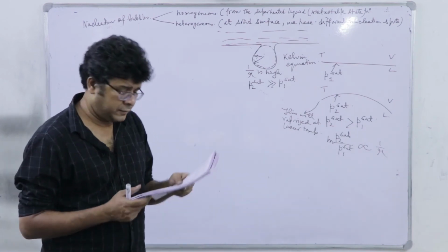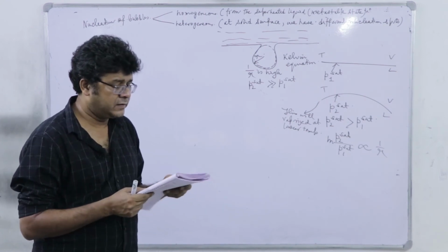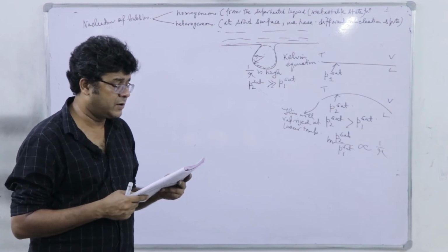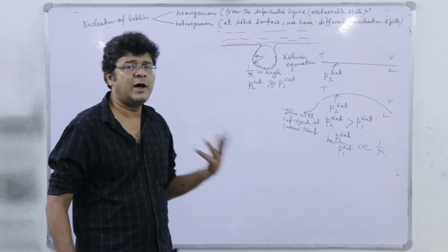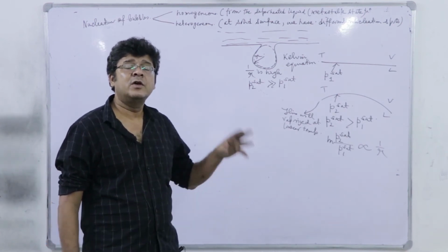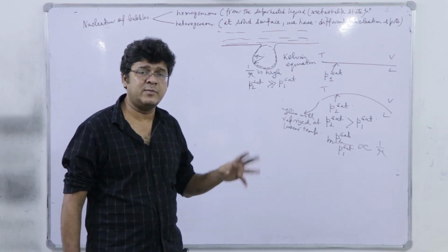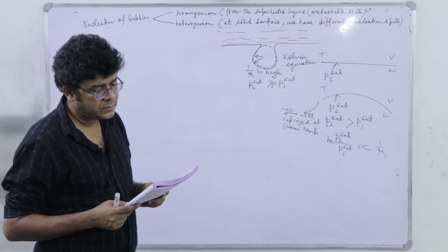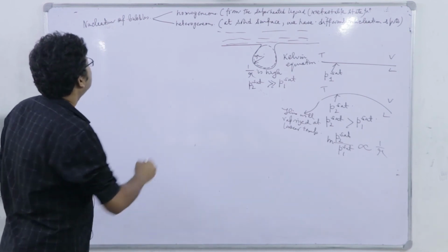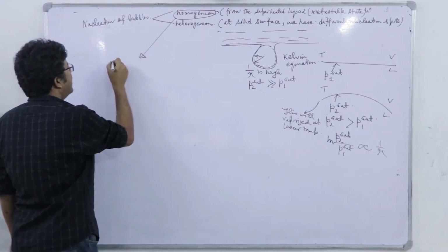So this is the reason why heterogeneous nucleation is not only technically favored, but it also has certain advantage, because we can achieve the same amount of vapor on a heterogeneous surface as in homogeneous nucleation, even if we think of a hypothetical situation where both are implementable with the same economy. So for homogeneous nucleation, we have a quantitative aspect.